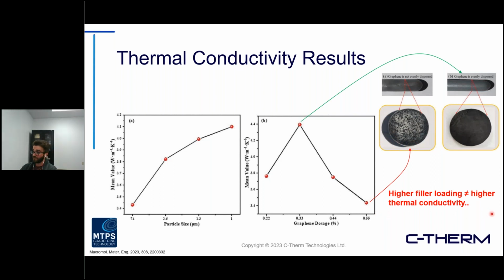So this is just one, again, secondary example where a higher filler loading does not necessarily equate to better thermal conductivity performance. So really, again, determining not only how much filler you're adding, but how well it's mixing and curing in that product can be really important to the end quality of the material that you're working with.